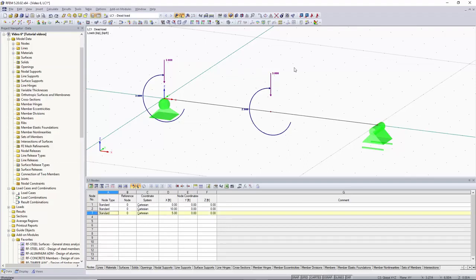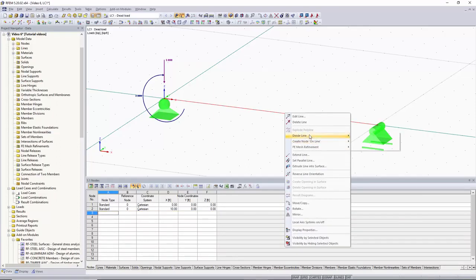And now I'd like to show you how to add nodes to multiple points on the beam instead of just the midpoint. We'll delete our loads, and we can also, by highlighting the node from left to right, select it without selecting the beam and hit delete. To add multiple nodes to the beam easily, we can go to the line, right click, and click on divide